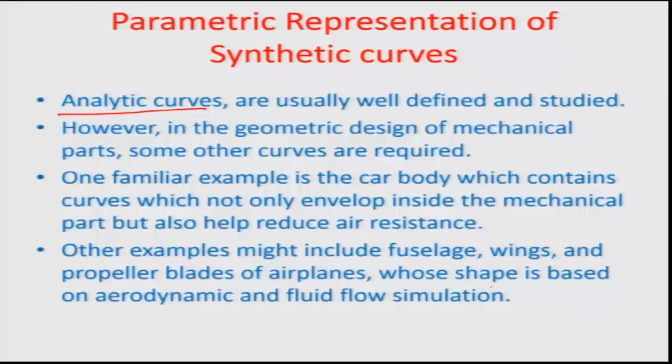Here we will talk about synthetic curves. Analytic curves, as you have seen earlier, are usually very well defined in terms of the functional relationship as well as the symmetry which exists in terms of the parameter which is taken, so the definition, whether parametric or non-parametric representation, is quite simple. However, in the geometric design of mechanical parts, there can be an extremely complex contour which may be plotted by a bunch of different curves rather than these standard analytic curves.